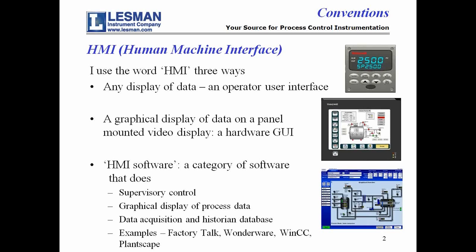The other thing that I want to distinguish between is programming and configuration. With programming, you have to know a language that has a set of rules and a syntax. You have to develop your own logic. You start with a blank slate, a blank page, and build everything, comments and everything. An example of this is structured text. In comparison, there's configuration. Configuration always has a menu. You use some kind of menu navigation technique, typically push buttons. You get to a given parameter, and you select from a variety of choices what you want that parameter to be. That's menu-based configuration.